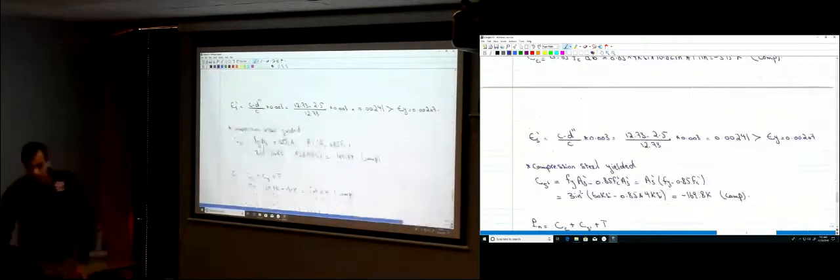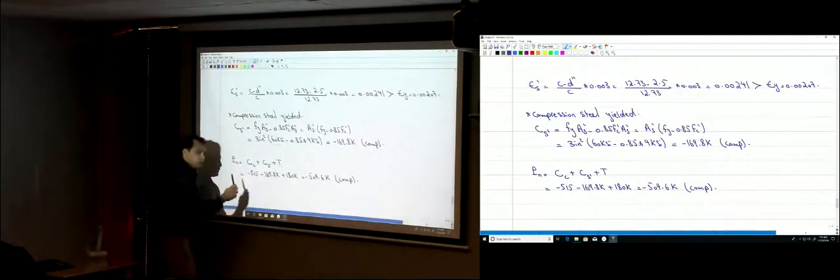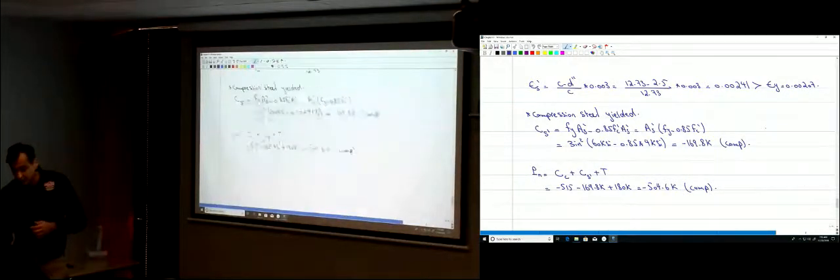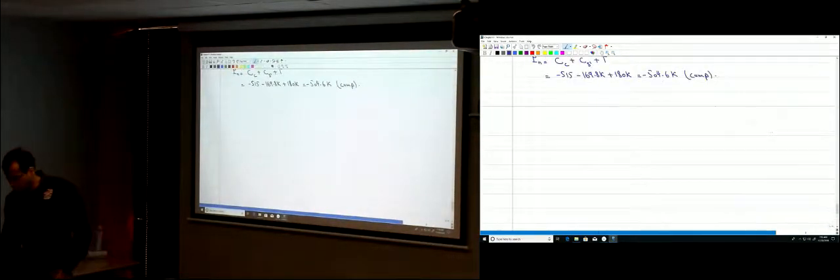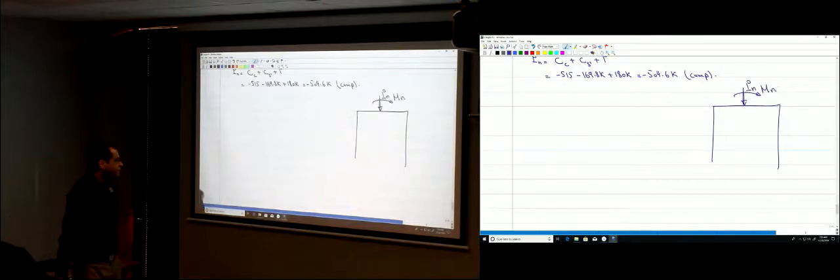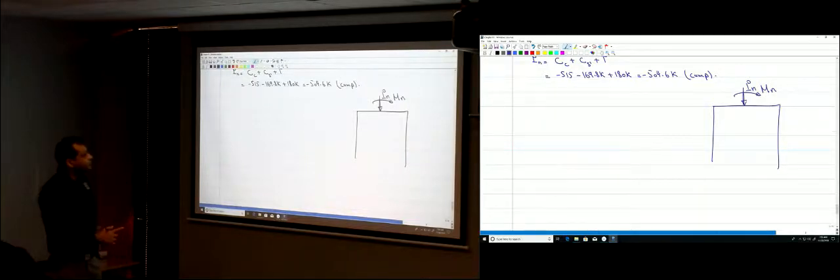So now, since we have the three forces applied on the section, the summation of them is equal to the nominal axial force applied on the section. Now, for this section, if this is the column, we know that there is a Pn and an Mn applied on the section that gives that strain distribution, okay? So now we calculated Pn.